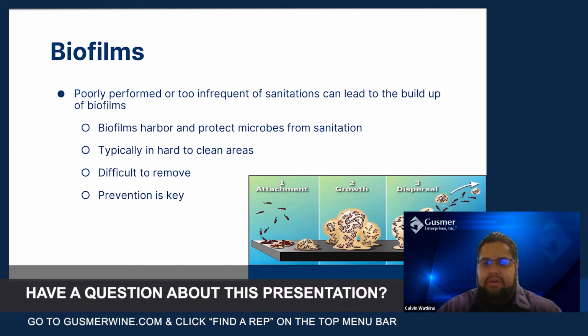Again, they're typically in hard to clean areas, dead legs, tees, a random corner in the tank. They're difficult to remove, but really the prevention of biofilms is key. You don't want them to build, because once they build, they're hard to get rid of.